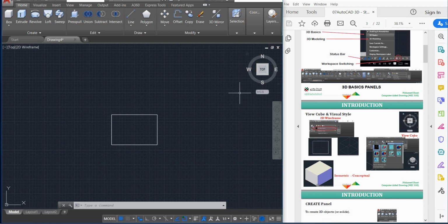If we decide to switch to another angle, if you just move the mouse without clicking anything, you're going to see lots of things show up. If you move off, these things are hidden. For example, you're going to see some of these arrows. If I press on this arrow, you are telling AutoCAD, please give me a view of this object from this angle. If you press on that arrow, you are asking AutoCAD to give you a view of the object from that angle, and so on.